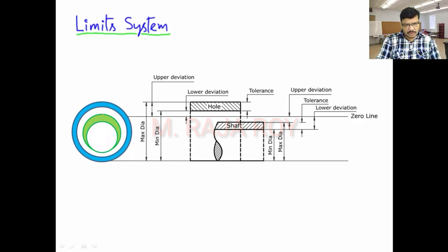That means this is the total variation in the shaft. Now coming to the hole, this is the half of the variation. Here another half is there. Now to represent it conveniently, assume that this shaft is touching this hole somewhere here. Shift it to this place. Now this entire assembly you shift downwards such that this half of the portion of the variation in the hole will shift to the top side, and total variation you can see in the top side only. Now shift it like this.